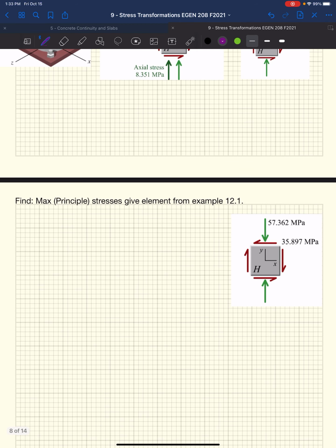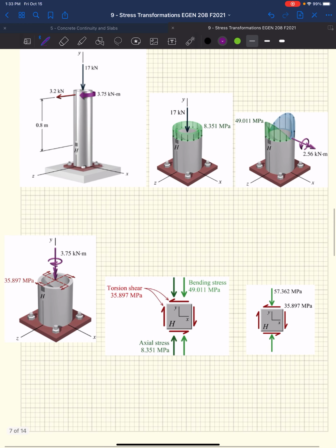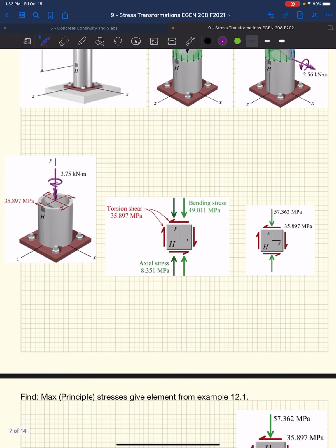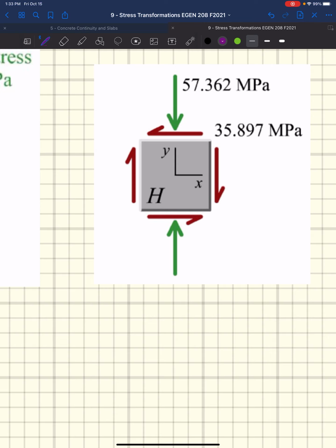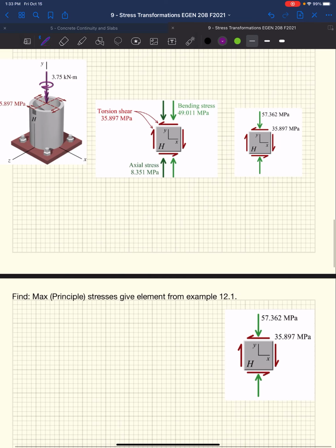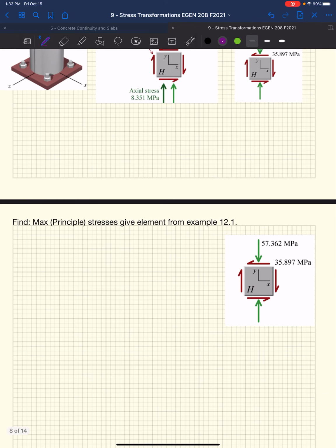And again, if we went through the same process, once we had this known stress state, we could get asked a number of things. If we were looking for the worst case stresses in this pipe, or flagpole, and we wanted to know what orientation those stresses are acting, we can use our known stress state, this stress block that we developed here. We can plot it on Mohr's circle, and we're going to figure out what our principal stresses are, the max stress without shear stress.